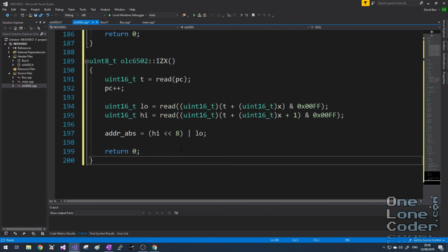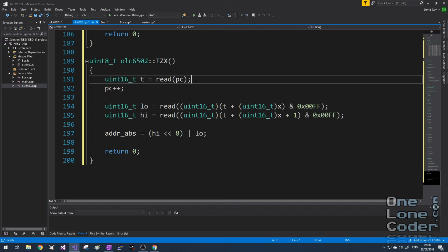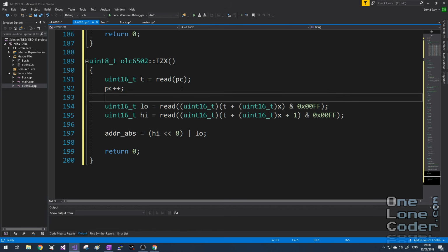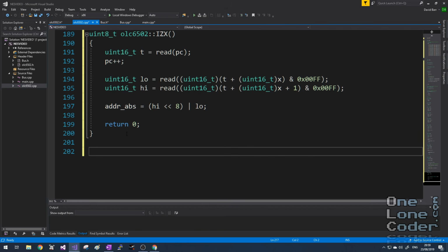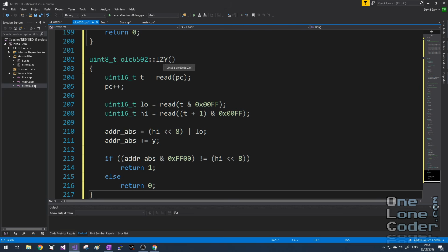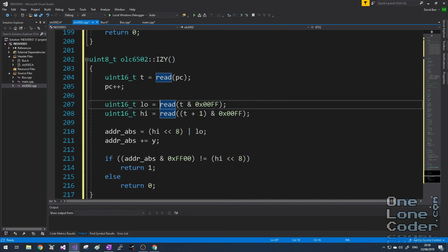Here we've got indirect addressing of the 0 page with X offset. The supplied address references somewhere in the 0 page. And from that location, we offset that 1 byte address by the contents of the X register to read the 16-bit actual address we need for the instruction. And rather confusingly, we've also got indirect addressing of the 0th page with a Y register offset.